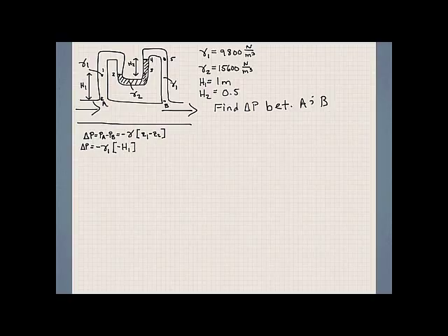So our next interface point is going to be between, we're going to start at point 2, which is the interface between gamma 1 and gamma 2, and we're going to end up at point 4 of this diagram. That height it's going to traverse is h2. So let's go ahead and write that. So we have gamma 2, and it's traversing a height that is lower, so we're starting off at a lower point. So this is going to be negative h2.